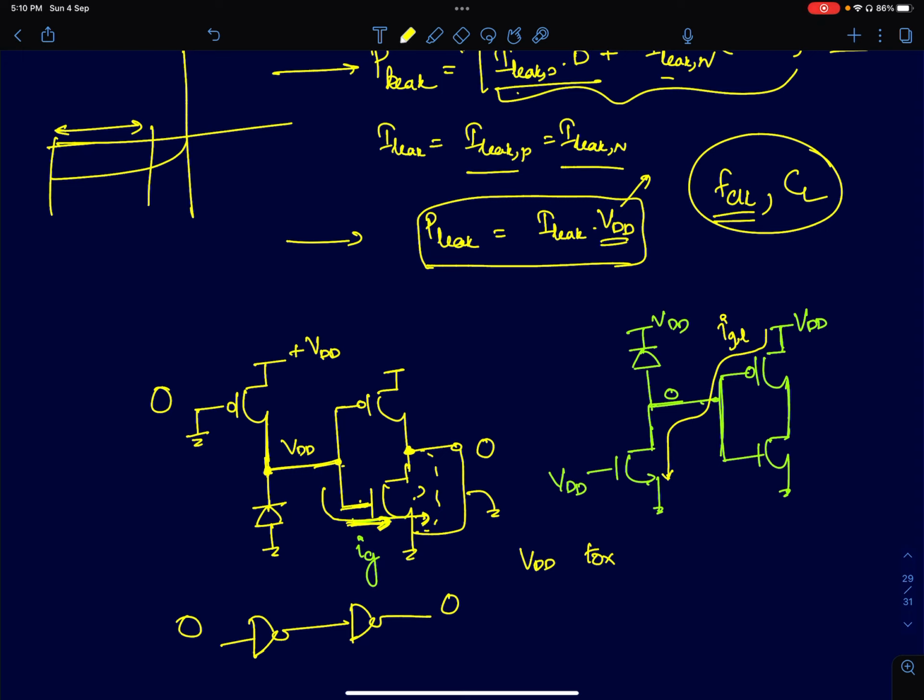So to complete the discussion, the other part of the gate leakage is if I'm applying VDD. Let's say I apply VDD, then I would expect the output to go to VDD, and this PMOS device is fully conducting. So for gate leakage to take place, you need to have a finite VGS. Zero VGS will not lead to a gate leakage. So that's why I did not consider a PMOS for gate leakage in this example.